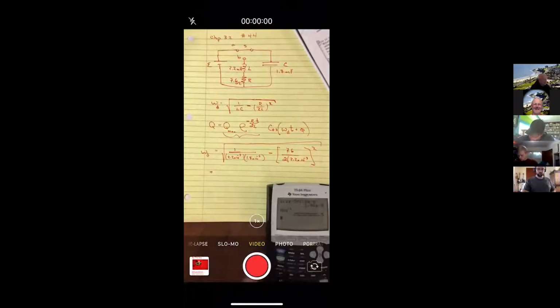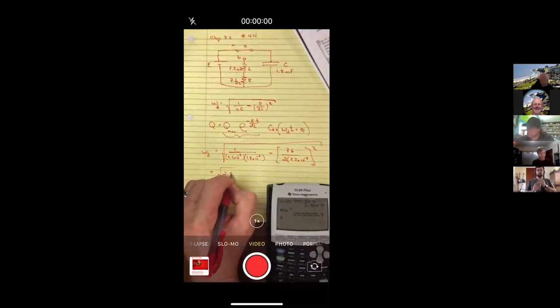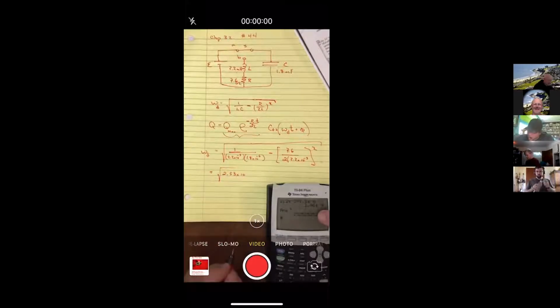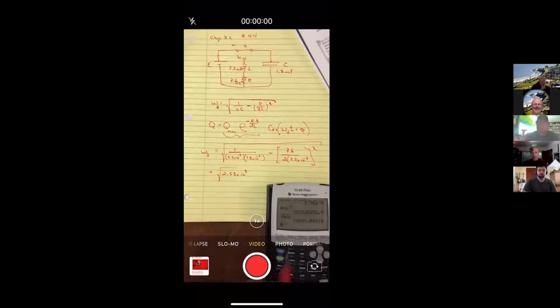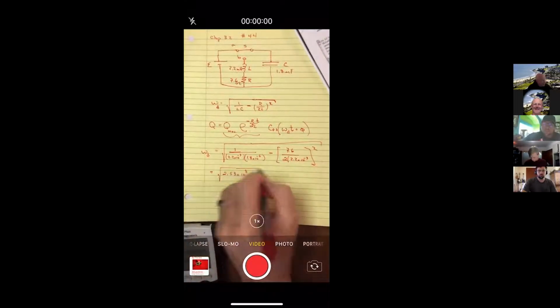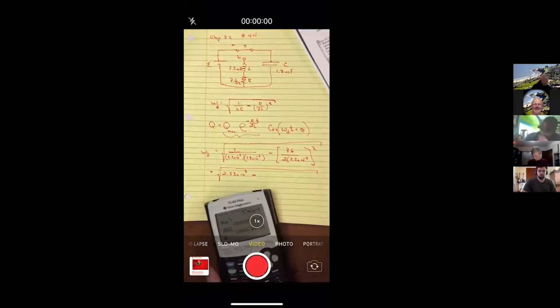And taking the reciprocal of that would be 2.53 times 10 to the 8. And just out of curiosity, if that's all there was, this would oscillate at about 16 kilohertz. But we're going to subtract off, and so this is going to lower the frequency because of the resistance a little bit.